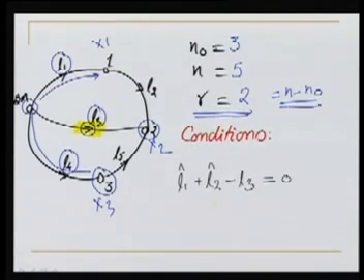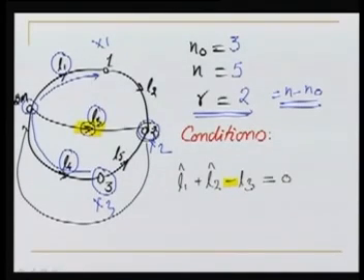So the sign, this is why I have used minus here. Further, we have another loop, and in this loop, if we start from the benchmark, go to point 2, then come back through point 3 to benchmark. We can write for this loop as L3 hat minus L5 hat minus L4 hat. This is equal to 0.